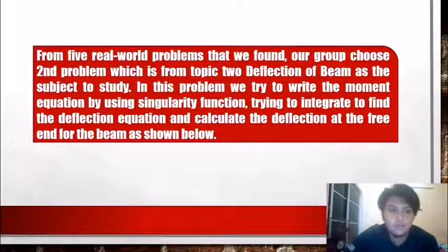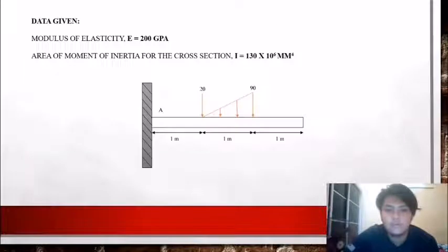Today I will discuss the calculation. So the first one, from the 5 real world problems that we found, our group chose the second problem, which is from topic 2, deflection of the beam, as the subject of the study. In this problem, we try to write the moment equation by using singularity function, integrate to find the deflection equation and calculate the deflection at the free end of the beam as shown below.